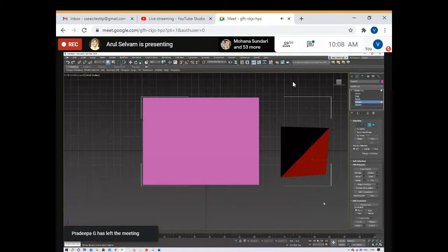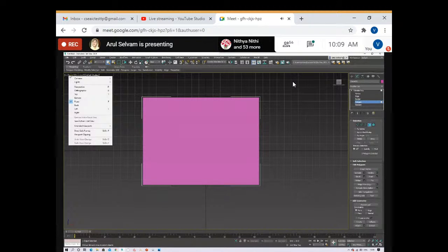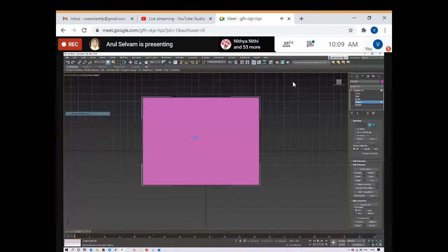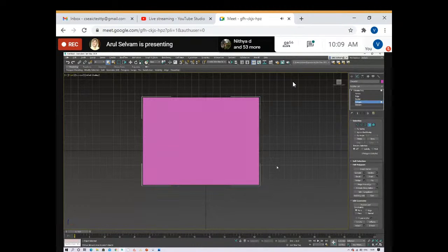So what I'm going to do is delete this part, and in this particular plane, we have 2 tri-meshes, 4 vertex points, and 1 polygon. To see the details, we have a statistics option in 3ds Max. I'm applying this option and can see 1 poly and 4 vertices.